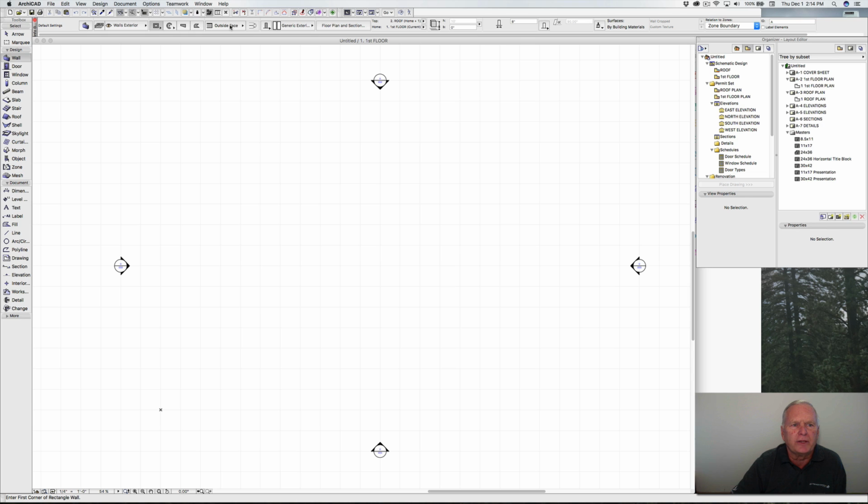Move along here, make sure that our reference line, that's that dark line you see right there, is on the outside face. If it isn't on yours and you're trying to follow along, just click on that and set it. Move here, this is a type of wall.